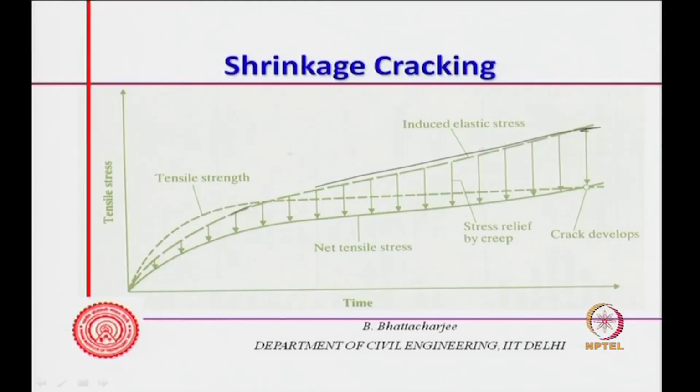This might be the induced tensile stress because of the restraint, and this will change with time, because shrinkage will increase with time, therefore, stress will increase with time, right. And this is the tensile strength. So, in the beginning the shrinkage stress could be less than the tensile strength, but if it crosses the tensile strength, cracking would come.